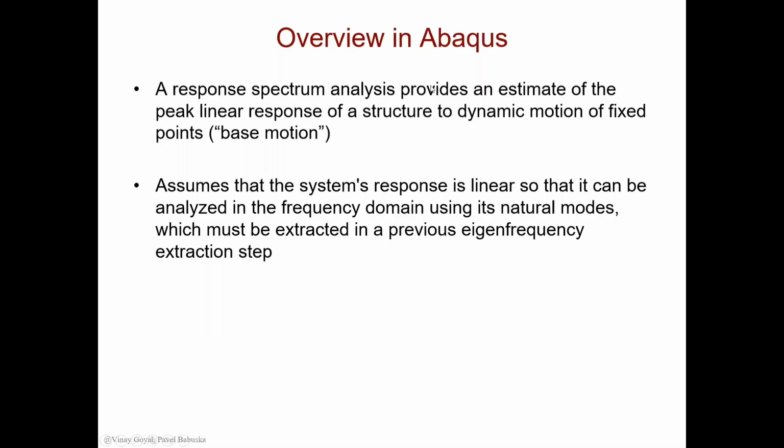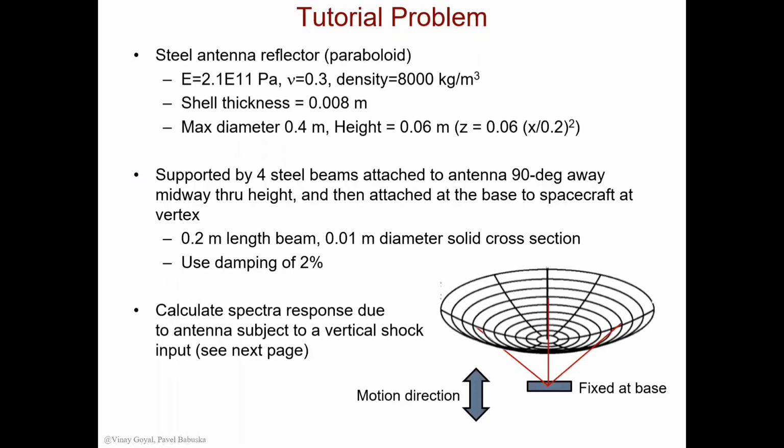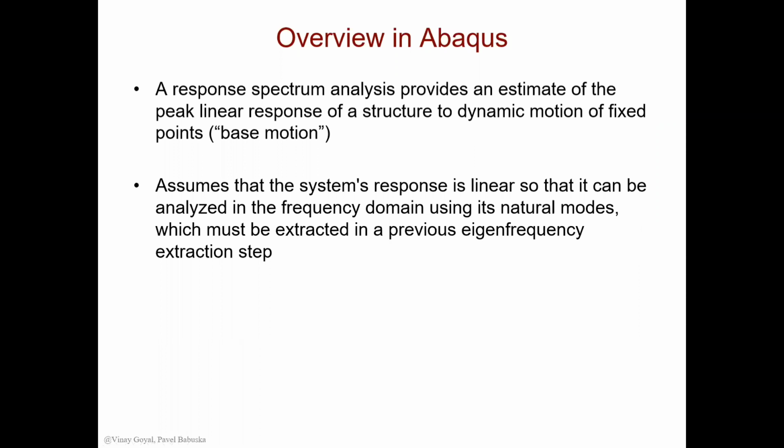The response spectrum analysis provides an estimate of the peak linear response of a structure due to dynamic motion of the fixed points. In this case, we have that fixed point here at the bottom of this antenna that has been connected with beams to a fixed base. We're going to assume that the system's response is linear so that it can be analyzed in the frequency domain using its natural modes, which must be extracted in a previous eigenfrequency extraction step.